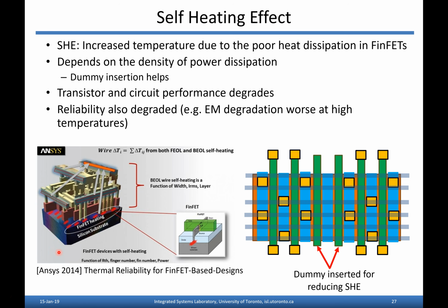So, as a result, it's quite common in FinFET layouts that you just see a lot of dummies inserted. I mean, you already see this in advanced planar technologies, but you get a lot of them showing up in 16 nanometers. You've got dummies put in everywhere. And sometimes it's just to give some extra space for the heat to dissipate, right? Avoid these self-heating effects. But, you know, again, because everything's got to be in a regular pitch, you can't just leave more space. You've got to put these dummies in there. That's actually the easiest way to do it.